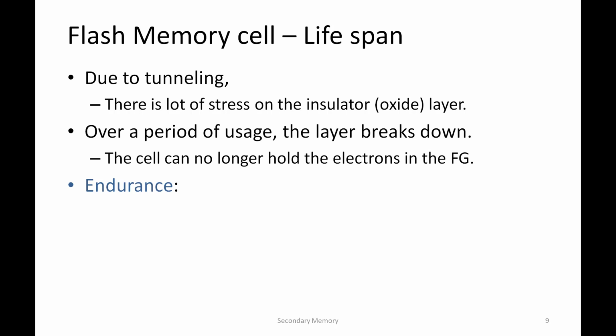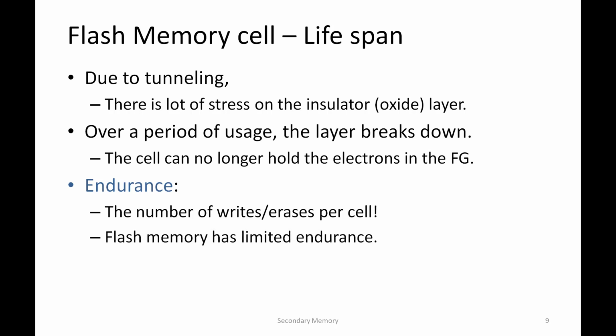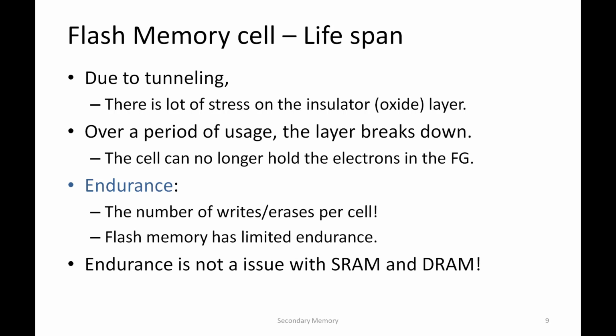Here is one technical term, endurance, which is defined as the number of times we can write or erase a cell. Because of the tunneling effect, the flash memory cell has limited endurance. When it comes to SRAM and DRAM, we have never discussed endurance because practically they have infinite endurance.